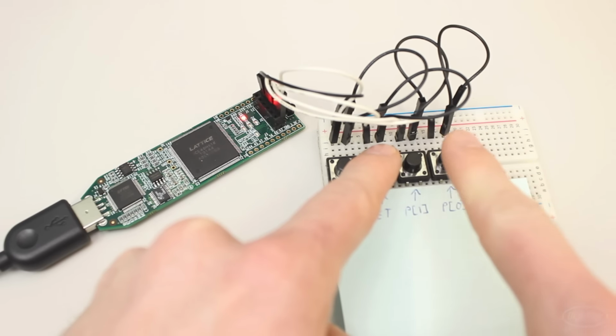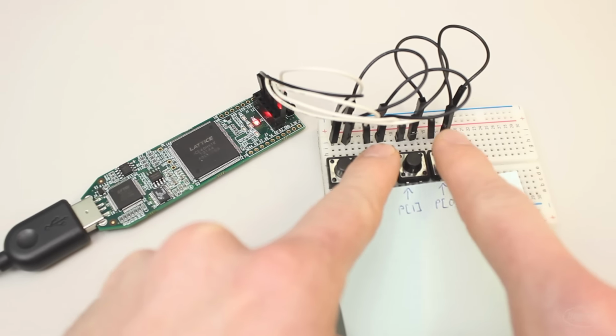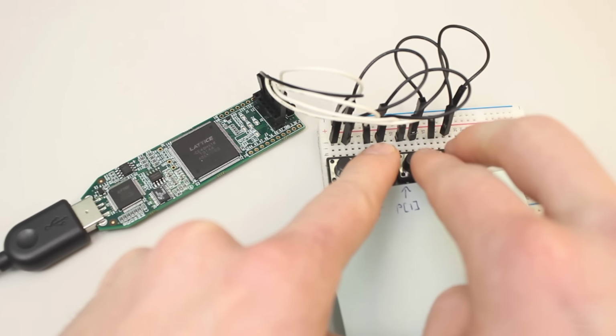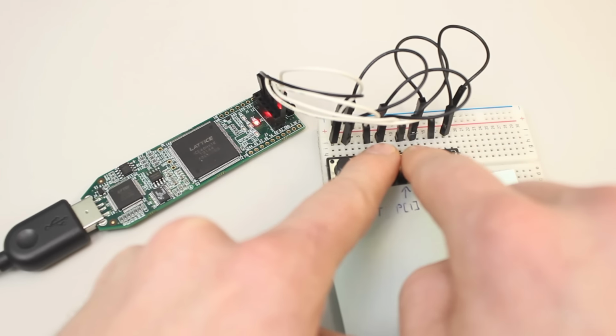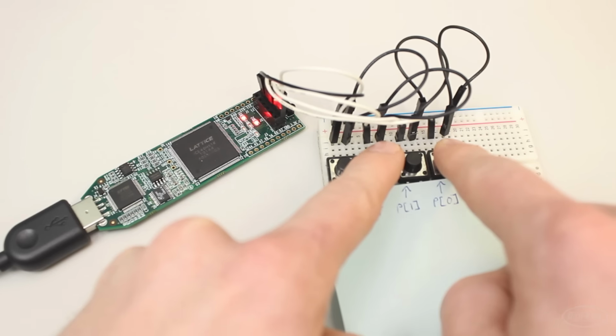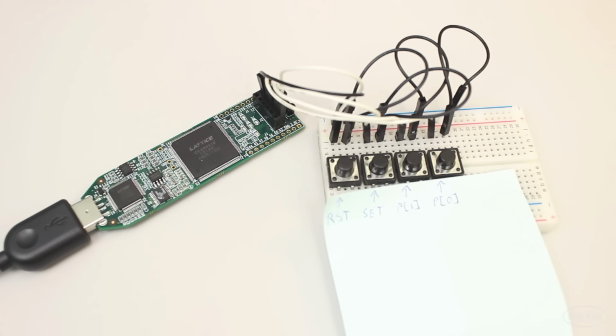I do another pattern, say 01, and set that into the next memory element. I'll continue logging 00, 01, 10, 11, 10, and 01. The sequencer will record those values to memory. It only needs to be 8 elements long. During this whole time, the sequencer is playing the sequence on the LEDs, 1 element at a time. When it loops back to the beginning, it should play that exact sequence back to me, 0, 1, 0, 1, 2, 3, 2, 1. Note that you'll likely need to use many of the concepts and modules from earlier episodes.